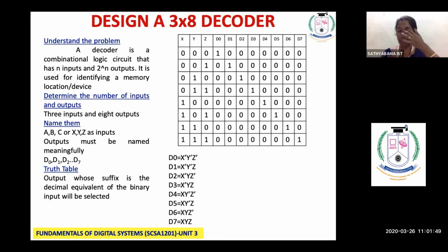Suppose the microprocessor has to address only two devices, I mean, has to select one among the two devices, it just needs one wire to be connected to both the devices. So from the microprocessor, a wire will go to the printer buffer. From the microprocessor, another wire will be going to the keyboard. If that wire carries a 0, then we can assume the keyboard is selected. If the wire carries a 1, then we can assume the printer buffer is selected.